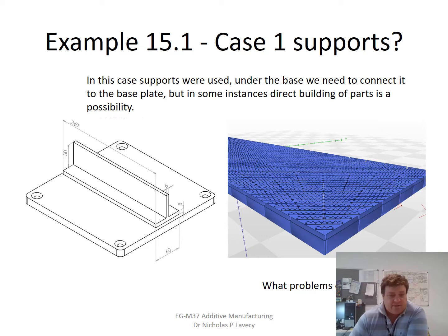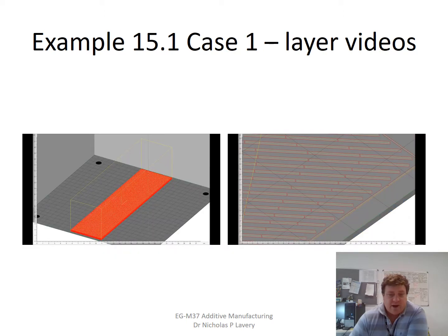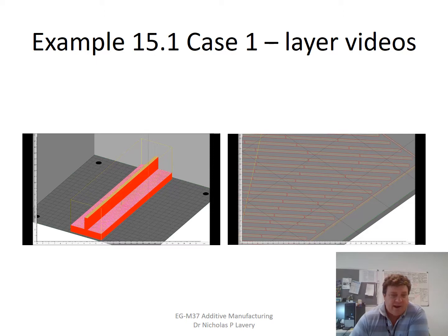and for a relatively thick component, which means that we are going to possibly have a lot of residual thermal stresses induced, which will lead to high residual stresses within the part. If we look at some of these videos, you can see the build plan as a series of every few layers we pick out.